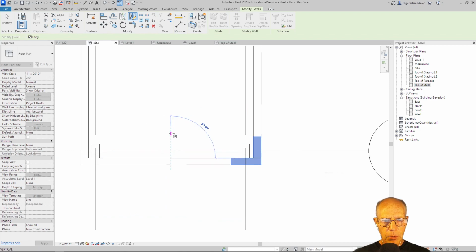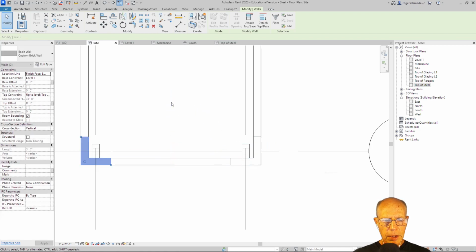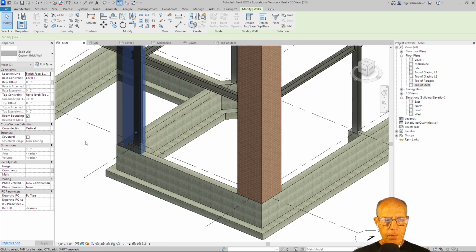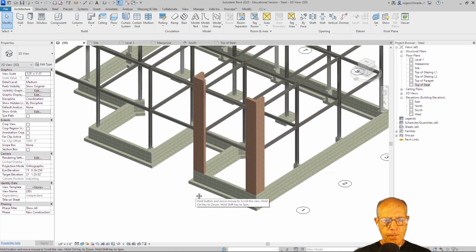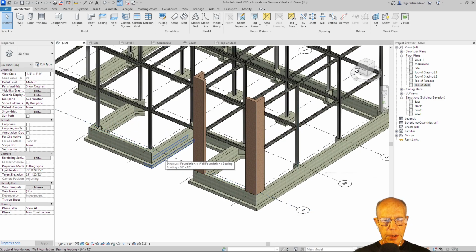If I grab that and pull straight up using that mirror command up there and the selected walls, I can make a duplicate right on the other side. And let's just take a look on that to verify. And there we have 2 of our columns done for us. And we want another 2 columns over here. So let's go ahead and do that now.